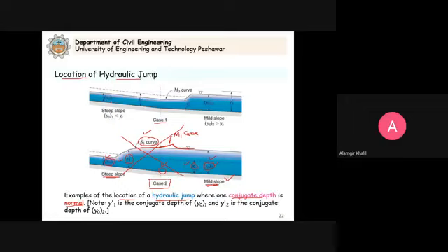Let us explore this case 1. Now in this case, we determine this normal depth using the Manning's formula. The critical depth you can calculate using the equations that we already discussed. So you will get this dash line. Then you can calculate this normal depth, again apply the Manning's formula. Now for this normal depth, I calculate this y2 dash, which is the depth upstream of this.